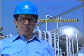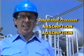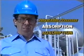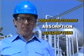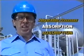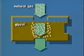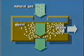Dehydration uses the processes of absorption and adsorption. The term absorption means the removal of water vapors from a gas stream by contact with a liquid desiccant. An example of a liquid desiccant would be glycol. Natural gas and glycol come in contact, and the desiccant absorbs the water from the gas.